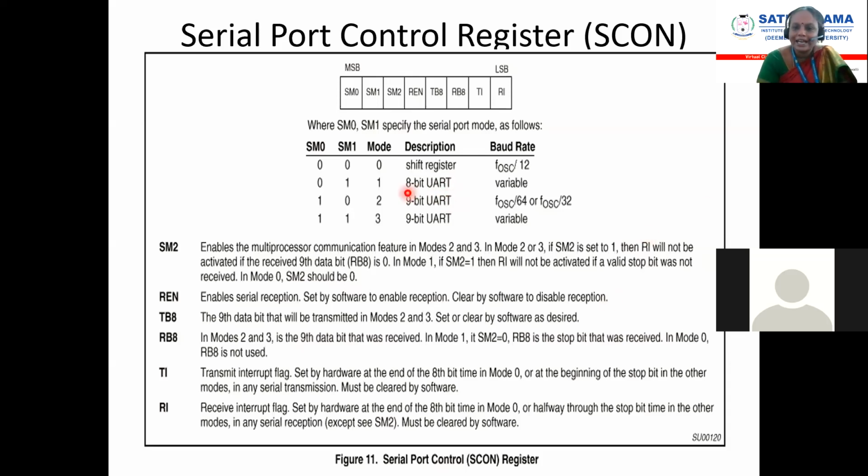Okay. So here we are sending 8-bit UART. Here, 9-bit, actually we can send only 8-bit, along with the start bit and stop bit, which I didn't include. But 9-bit means it can send only 8-bit, so if it is 9-bit, I have to enable these 2 bits, TB8 or RB8. Did you all remember? If I want to send the 9th data, whether in transmission or receiving,